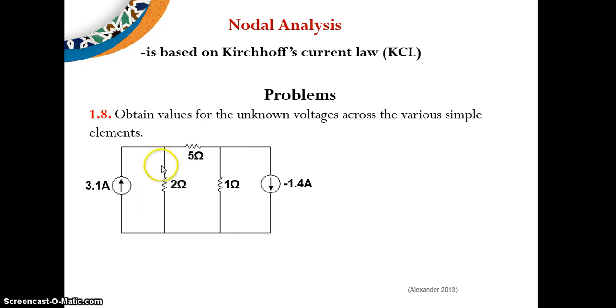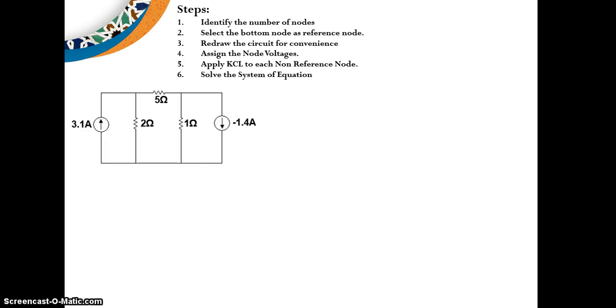As I told you, the basis of nodal analysis is Kirchhoff's current law. For doing nodal analysis, I have listed the following steps. If you follow the steps in order, we can solve nodal analysis easily. See here, step 1 for this circuit: identify the number of nodes. Look here, this branch, this branch, this branch meet at this common point. I take this whole thing as one node, marked as node 1.